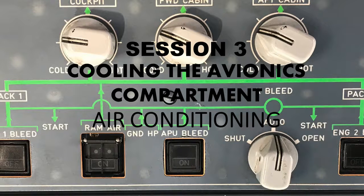It's going to be partially open, and then you're going to have the skin exchanger outlet bypass valve open, just like you would have in the closed circuit. That's going to be open, as well as the inlet bypass valve, which will open automatically. Again, the whole idea here is allowing that cool air to enter the avionics compartment.